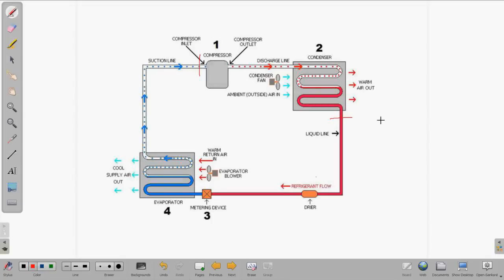Now let's take a look at the difference between a system that has a low load, a plugged filter, a collapsed return air duct, a dirty coil. You don't even need to go look for it. You're going to know that it's an airflow issue from one of those reasons, or even a sofa pushed up against a sidewall return air. I've seen that happen quite a bit as well.